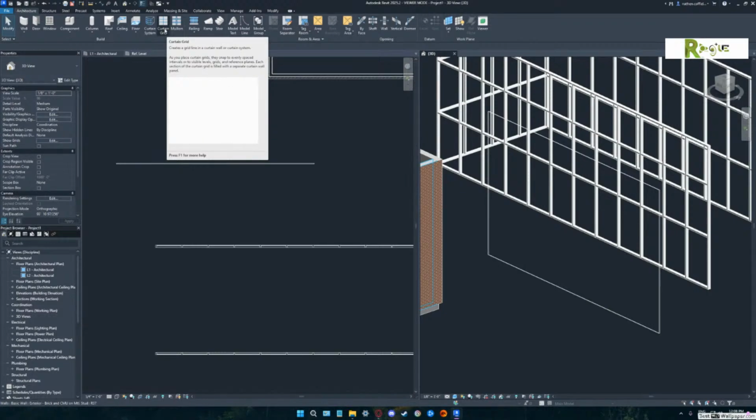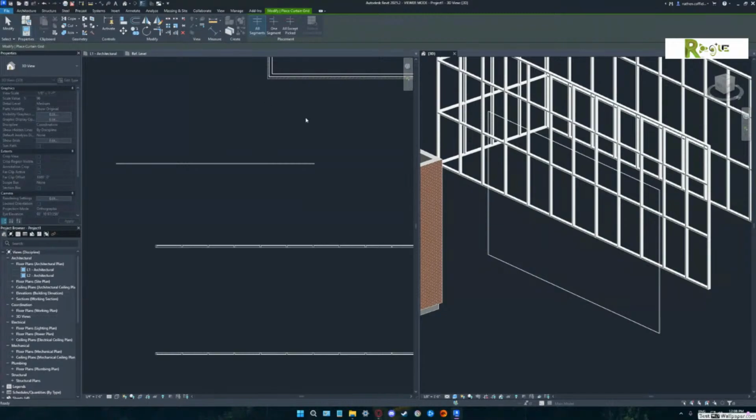So you hit curtain grid. If you hit the bottom edge, it's going to draw the vertical line. And if you hit one of the side edges, go ahead and click a couple, put some curtain grids in. Perfect. Do a couple, hit one of those grid lines that you just put in. There you go. You see how it's allowing you to put these grids in at a certain elevation. Yeah. Go ahead, put a couple in. All right. That's good for right now.